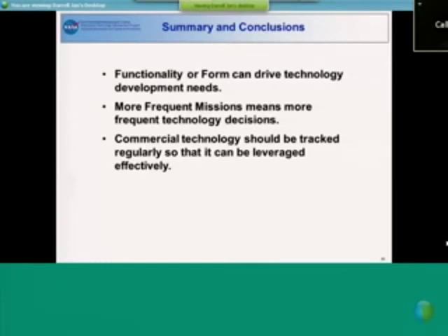Let's see, in the context we're talking about now, in the crew habitat environment, everything has to survive. Normally you don't get exposed to vacuum when you're in the crew habitat, but in case of emergency, it could happen. So everything that goes into the crew habitat has to be able to survive exposure to vacuum. It doesn't necessarily have to function while it's in vacuum, but once the atmosphere is restored, it has to regain its capability. There are also requirements for temperature extremes and electromagnetic interference and things like that.